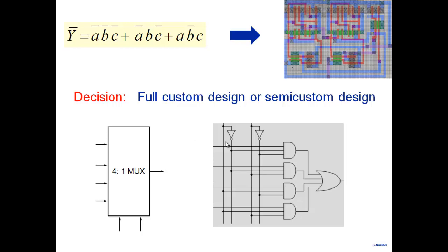Not only that, if I look at the delay, it has to go through a 3-input gate and then another 4-input gate and all that. The delay may also be large. It may satisfy your constraint, I don't know, but the delay in general will be large here.